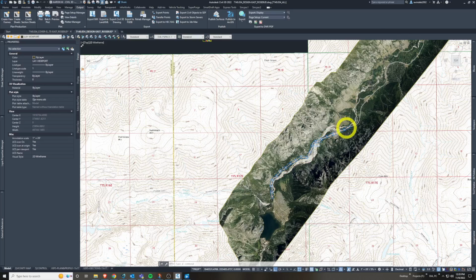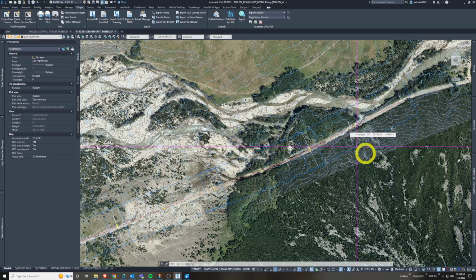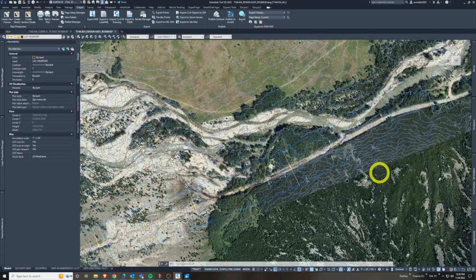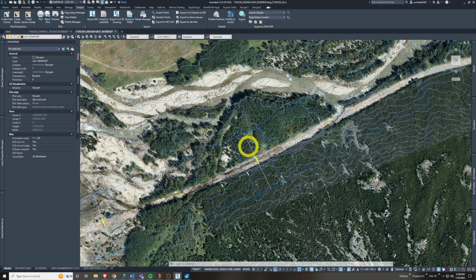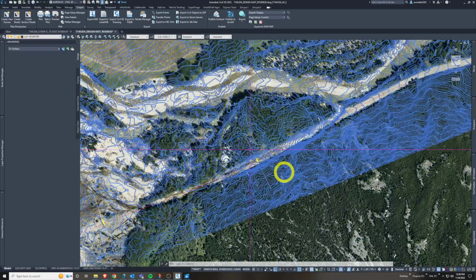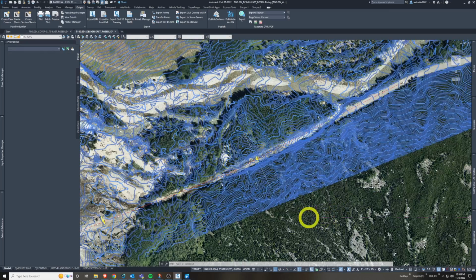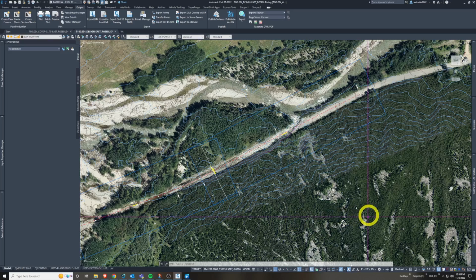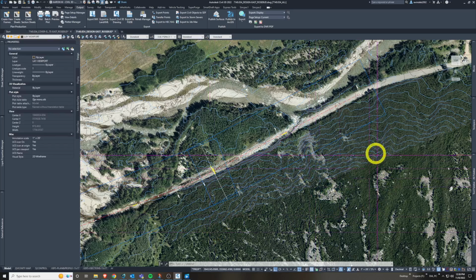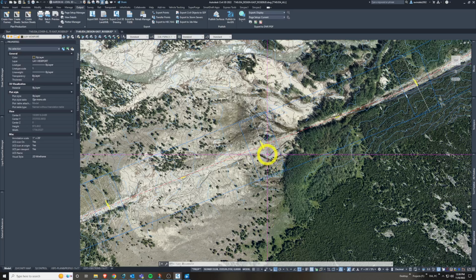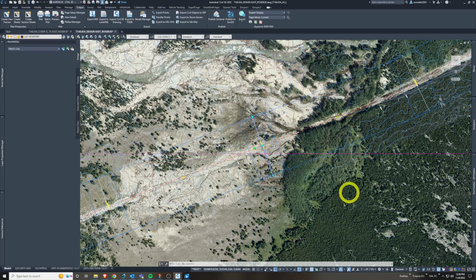This is a good time to inspect them, take a look at them. Honestly, they overlap quite a bit. But this is where the true match line is going to be. This is where it goes from one sheet to the next. The view frame is where the blue is, kind of where the sheet will overtake the match line. These lines here are where the sheet's really going to.